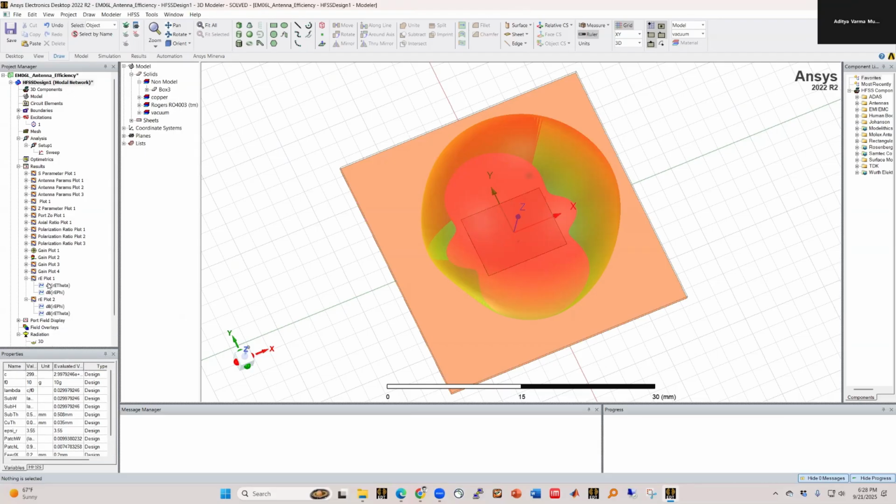But hopefully, if you think about that a little bit, it makes sense that really the electric field is along Ey, and in the E plane, in the YZ plane, Ey becomes E theta, and in the XZ plane, Ey becomes E phi. You can see that the electric field is along this direction. So along the YZ plane, it's pointing along theta. Whereas if you move slightly to the right, in this direction, you have Ey, and that is E phi, because phi goes around like this.